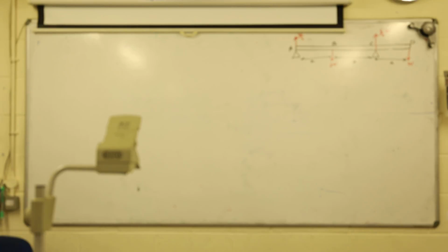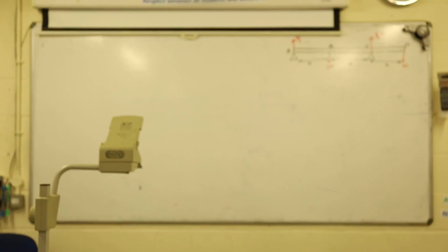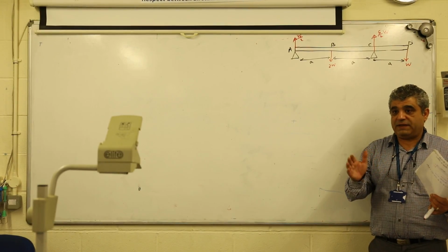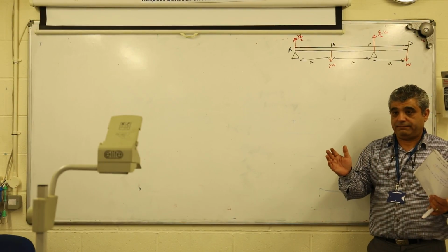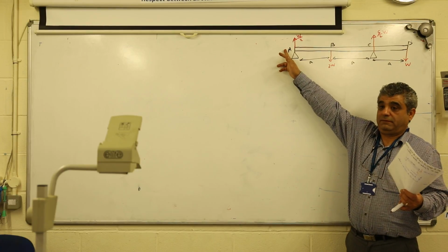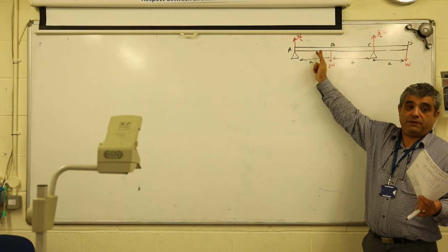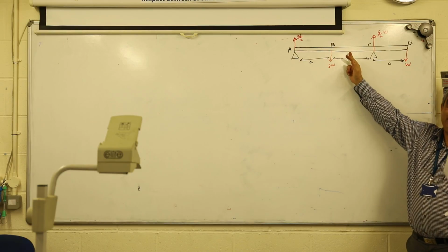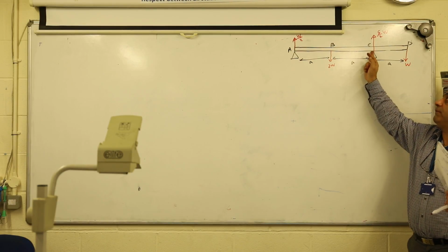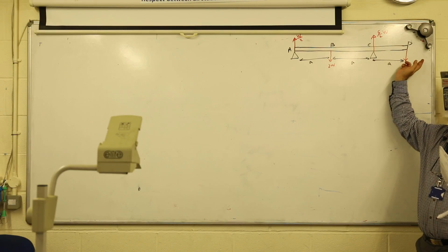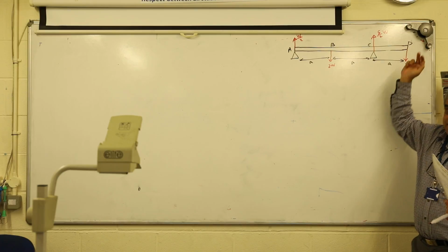How many cuts would it be in general? Oh, this one. 3. Did you hear that? 3. When we do the cutting, in order to draw the bending moment and shear force, before and after each concentrated level. Can I do before here? There's no big. Before, after, and before this one. And in here, after and before this one. And in here, after and before this one. And here we cannot cut.